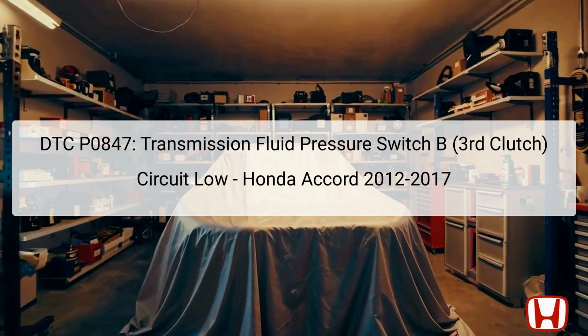The fail-safe function limits the vehicle's shifting capability to only third or sixth gear to prevent further damage until repairs are made. Effective troubleshooting is essential to ensure that the root cause is identified, which may be related to the electrical circuit, but not mechanical problems within the transmission itself.